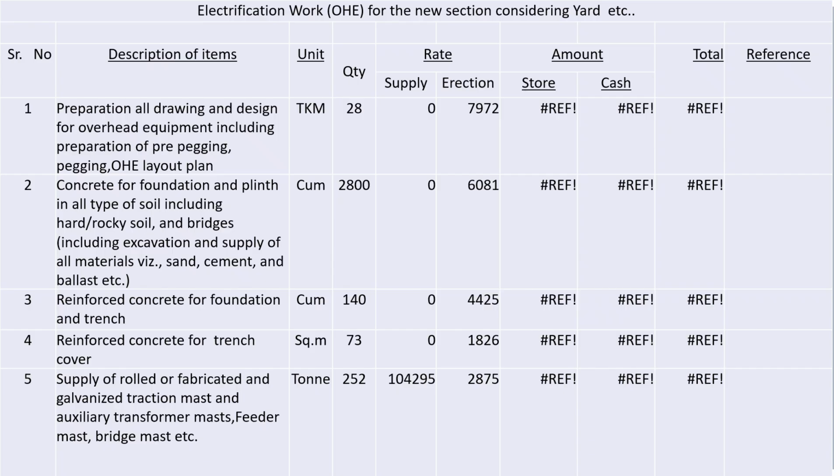Then somewhat they are controlling this isolator also by SCADA, remote control, supervisory control and data acquisition system. The isolator is converted into motorized isolator so that remotely they can operate it. These isolators are motor operated isolators. So many changes in the system, but according to the requirement of the client, you have to do all these things. So isolator may be manual, single pole or double pole.